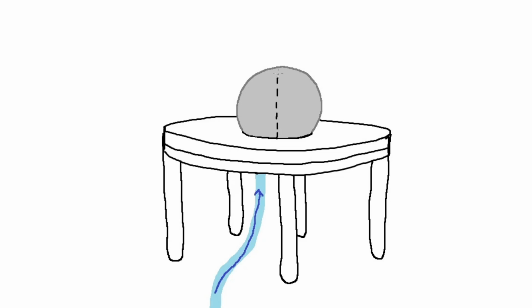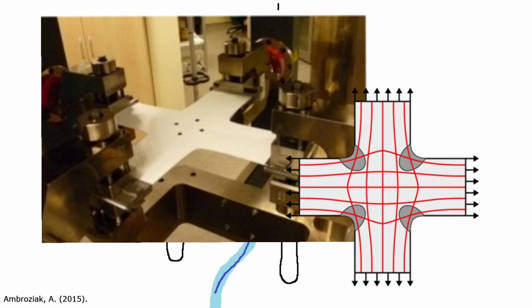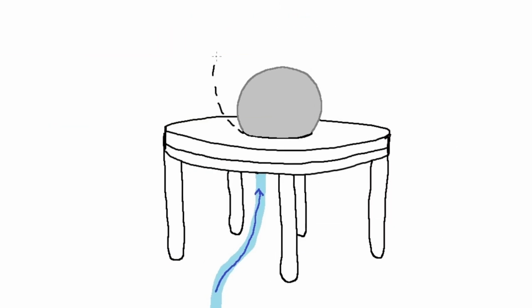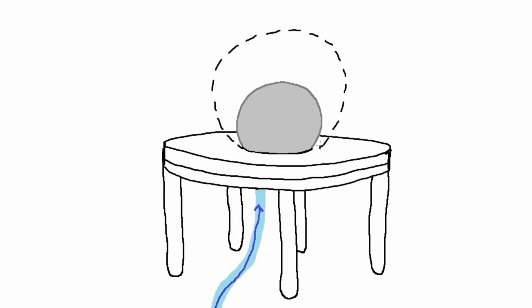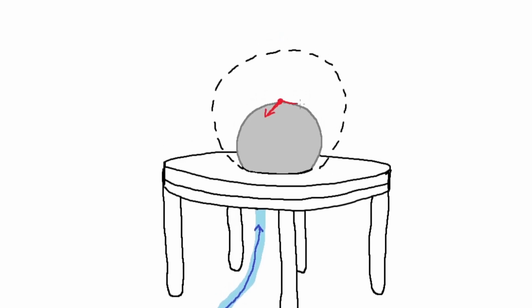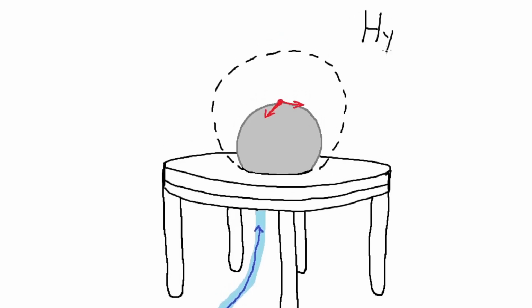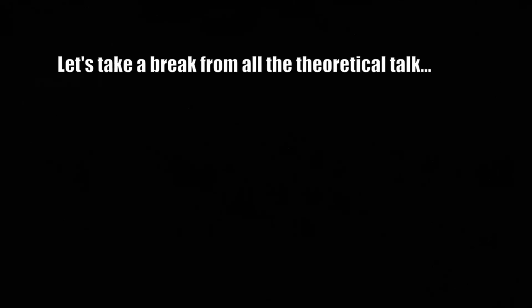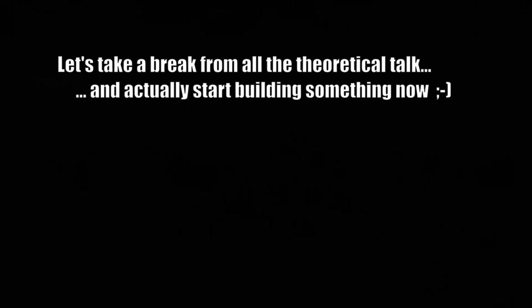Since the clamping conditions are rotationally symmetric, the stress concentrations within the material are minimized during deformation, in contrast to... Therefore, this method is able to reach larger deformation ranges, making it ideal for biaxial loading of hyperelastic materials such as Ecoflex 30. How this method provides the required material characteristics, I'll explain later on in the video.